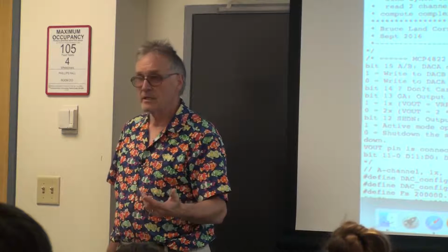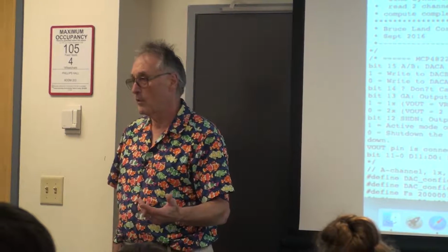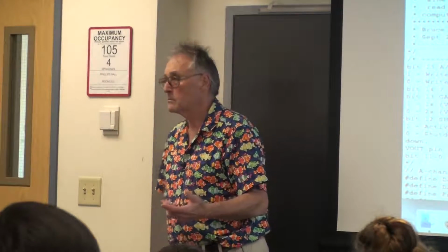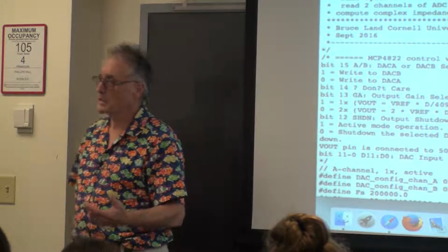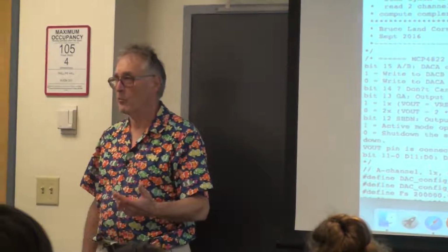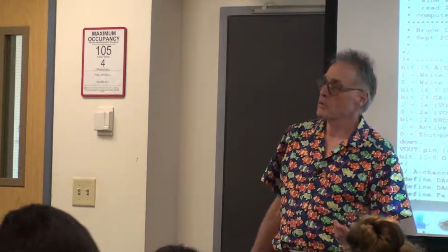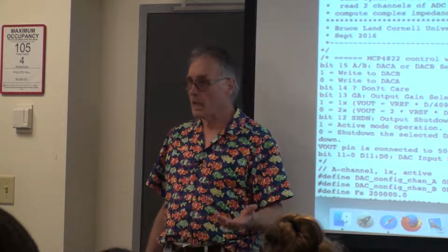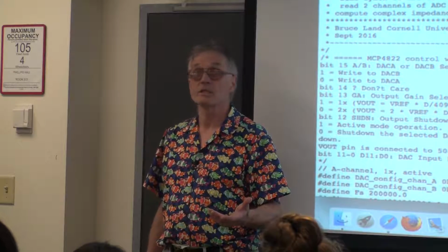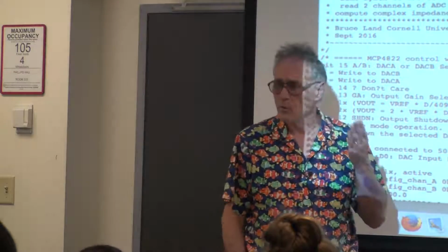The voice is going to be slower by a factor of 12.5 or 6.25, because it's all sampled at either 8 kilohertz or 16 kilohertz. Now you could go back to the MATLAB code. You could resample at whatever frequency you like. But you can only store, let's see, flash is 128 kilobytes.